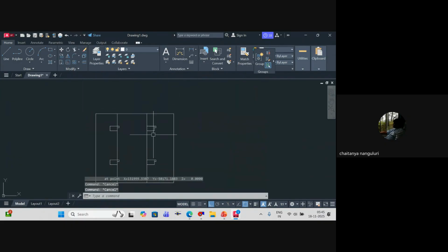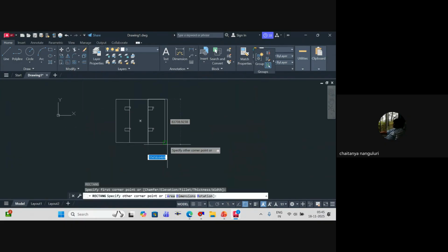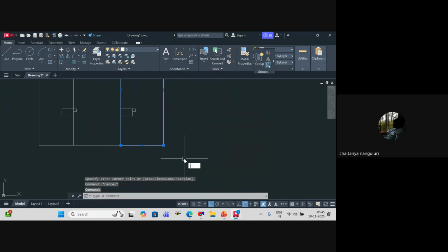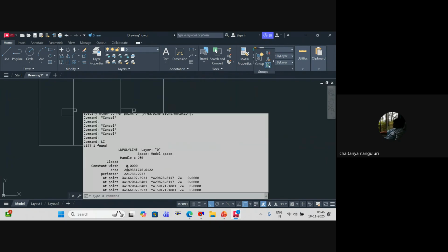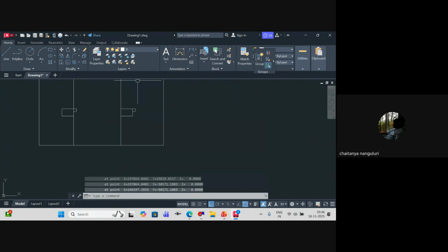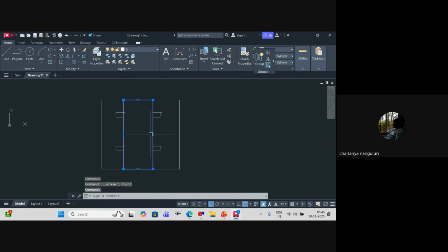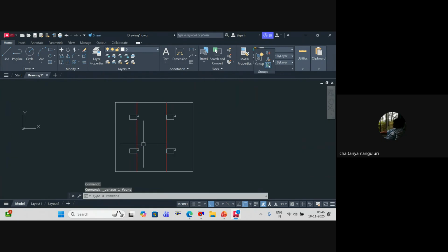If I see the areas over here, this should be lesser than 3000 square meters. 2700 it has come. Let me see the right side. I guess the right side also should be lesser anyway, but let me just cross check. Do 4, so we are safer. Yes, lesser than 3000 square meters is what we're doing. Now, at these locations, we wanted to place our nozzles.